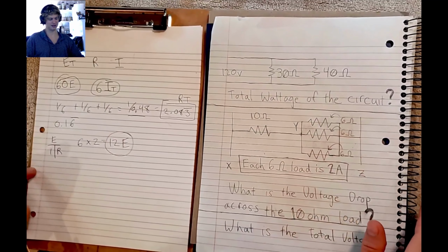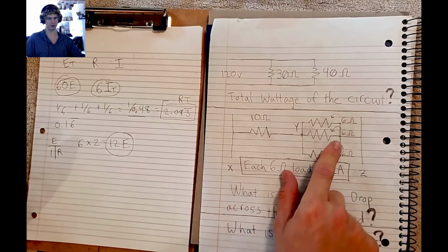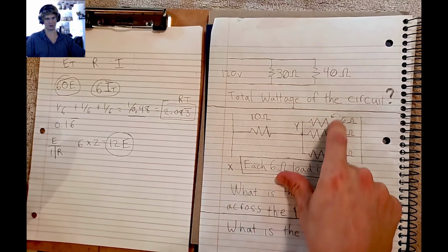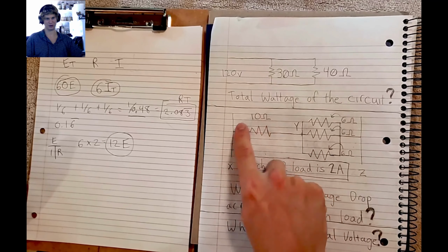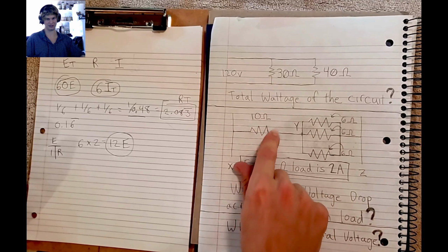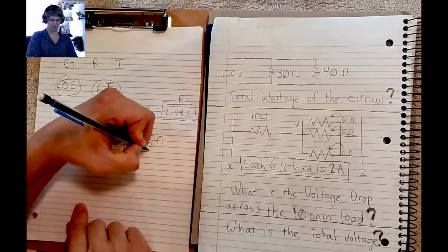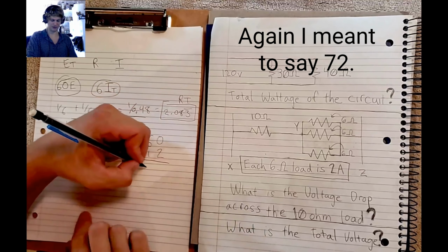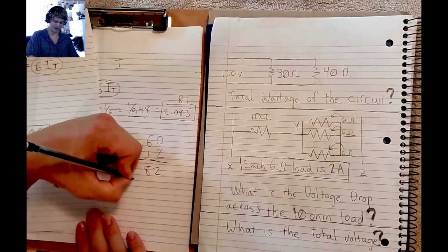And since that's connected to the resistor wired in series, the total voltage from these resistors wired in parallel is going to add to this voltage going through this resistor connected to it in series. Therefore, we're going to get 60 plus 12. When we get 60 plus 12, we have 72. So as you can see in this case, we got the same exact answer.